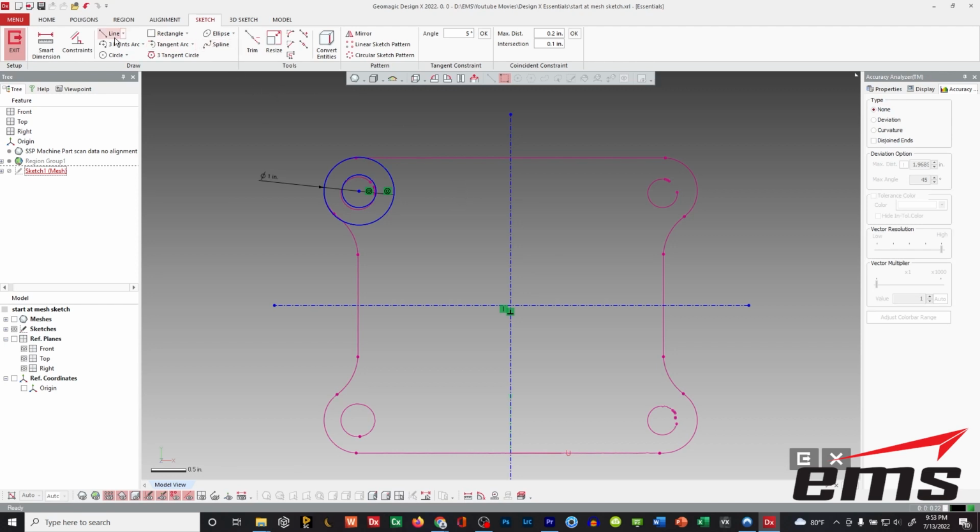Now, let's go ahead and draw some lines. So I'm going to start here, and I want to turn off that fit polyline because I'm going to pick, and then I'm going to bring this over here, and you can see when it highlights tangent. Okay, I want to do that. And then for this bottom line, again, I could pick polyline, but you'll notice when I do that and hit OK, I don't get the vertical constraint symbol.